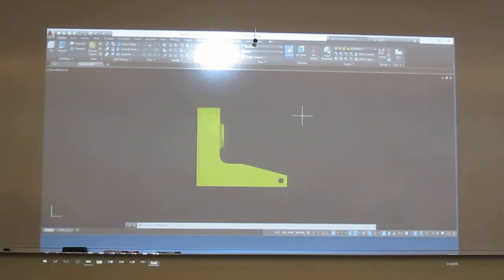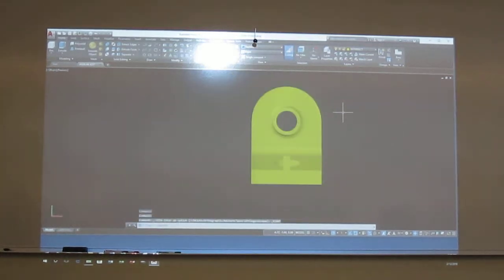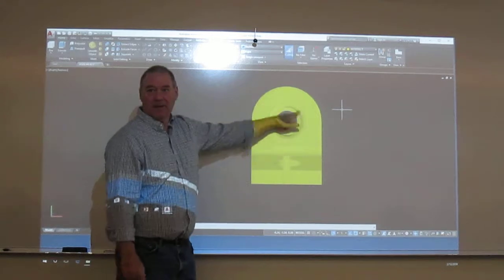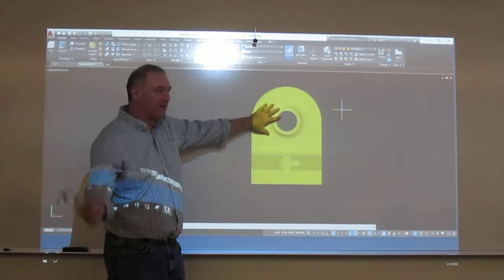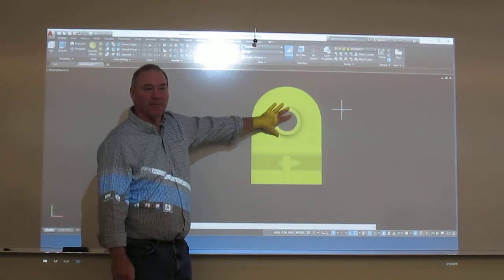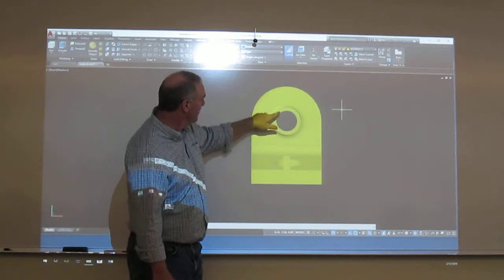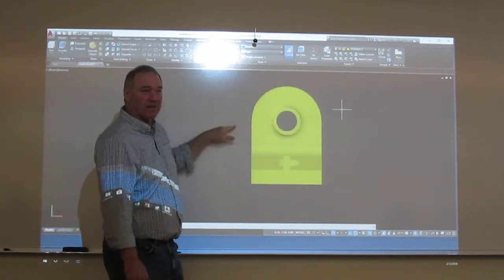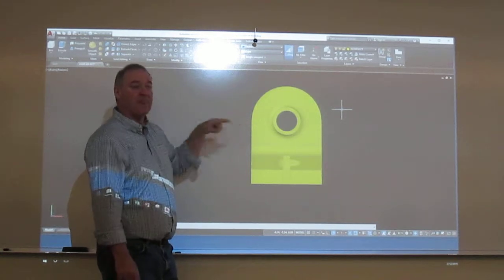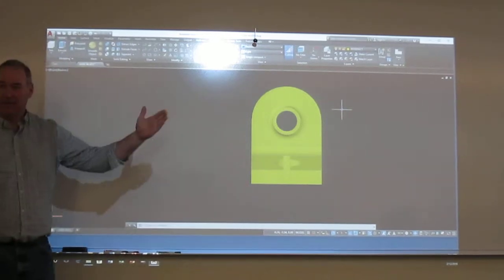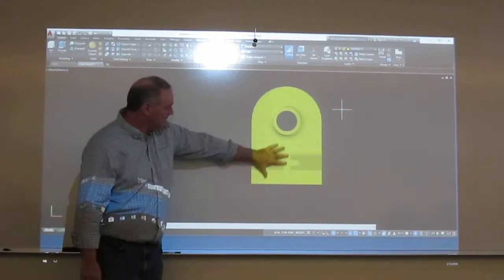From there, I'm probably going to a right side view here. Why? Because on the right side view, I give the total size description, shape and size of this piece up in here. And I've got to get to this orientation, whether it's your right or top doesn't matter, but I've got to get this orientation. Because I also got to locate, right? This has all got to be located, both this one, the negative, the positive, and this positive, all have to be located in this view, right? Locate positive and negative cylinders in the circular view. We dimension them in different views. I don't really get much down in here in this view.